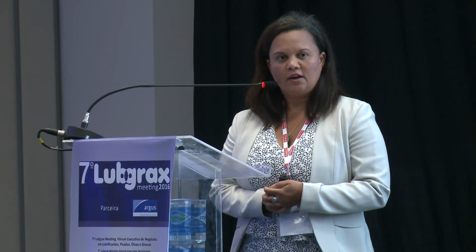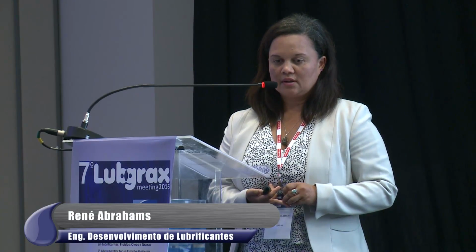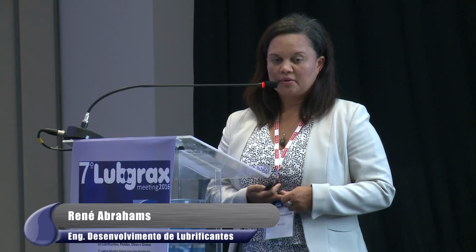Right, so because one of the oils in this study had a slightly lower viscosity index, I wanted to look at low temperature and high temperature rheology. So here, again, we have these pour points. This is a low temperature sweep. You see that the NYNAS greases are pretty stable at low temperature, whereas the group 1 grease requires much more strain or pressure to move.